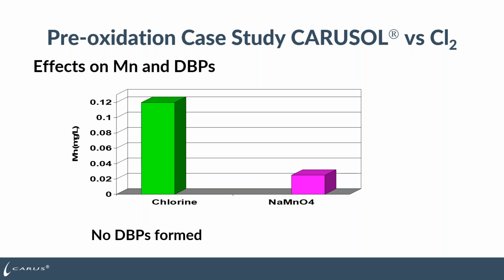And then they had their disinfection time in the clear well prior to going to the system, and were well below the THM standard leaving the plant, and very low levels out in the system. So they're able to remove everything in the plant and not have that issue of violating the disinfection byproduct rule leaving the plant.